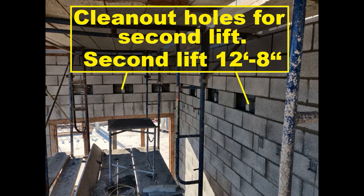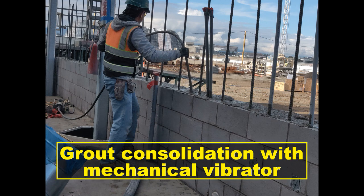If masonry has not cured at least 4 hours or grout slump is not maintained between 10 to 11 inches, place conventional grout in lifts not exceeding 5 feet 4 inches. Consolidate conventional grout lift and reconsolidate after initial settlement. For grout pours that are 12 inches or less in height, consolidate and reconsolidate grout by mechanical vibration or puddling. For grout pours that are greater than 12 inches in height, consolidate and reconsolidate grout by mechanical vibration.